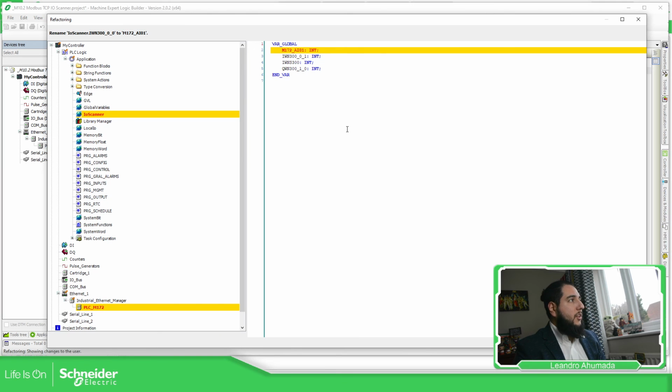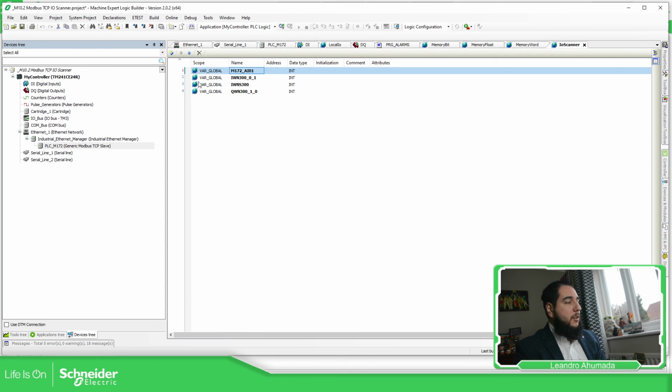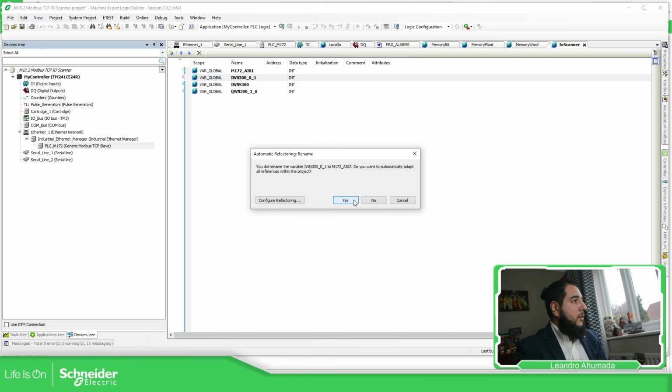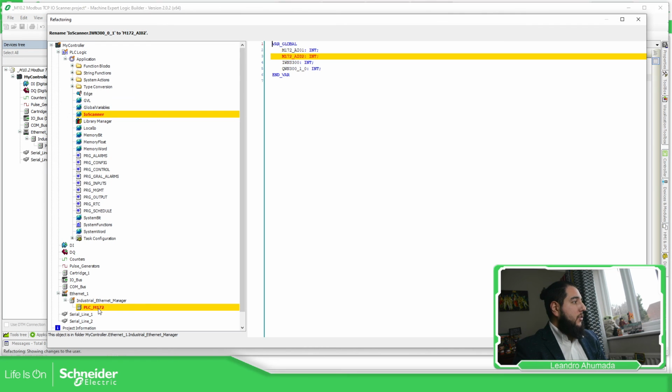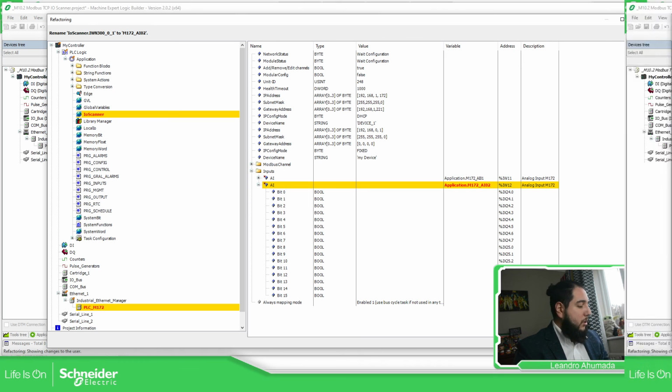So in this window, it basically tells you that in this GBL, this name is going to be overwritten, and it's going to be overwritten in all other places. Here I'm going to do the same for the other analog output. You can see it is also used over here in the other channel. This way you can change the variable in all the code that you have. I'm going to proceed with OK.